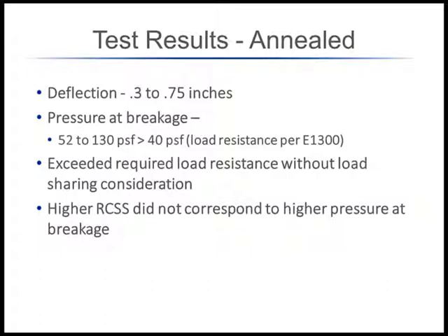So not only did we find that the fracture did not correspond to the damage in most cases, but also, at least using the current E1300, the strength of the glass still exceeded the load resistance, even without any type of load sharing. In IG units, there's a certain amount of load sharing between the outboard and inboard light, so that the load that comes in through the outboard light is shared. A certain amount of that is shared by the inboard light.